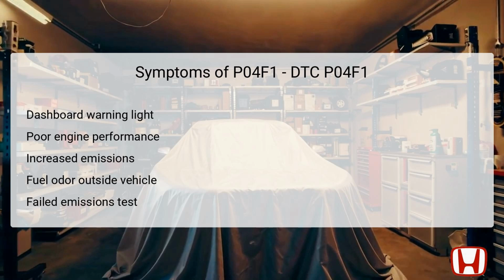The symptoms associated with DTC P04F1 can vary, from minor to significant issues impacting overall vehicle performance. One common symptom is the illumination of the dashboard warning light, alerting the driver to a potential issue with the emission system. Drivers may also experience poor engine performance, particularly during acceleration, as the fuel vapor system is crucial for efficient engine operation.